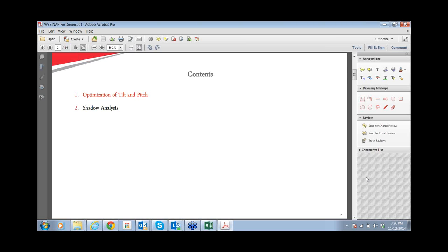And secondly, there is the water issue, because most plants are put up in barren land areas like Rajasthan and Kutch in Gujarat, where water is a very precious commodity. So you need a tanker that moves between these two rows, so you have to keep space between the rows for module cleaning access.